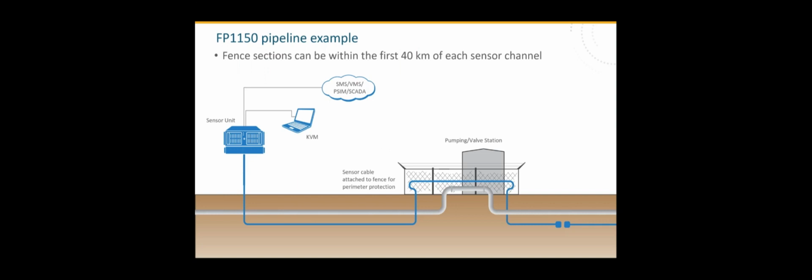And because the system is general purpose, you can do what the picture is showing here, whereby this cable is being used primarily in this little vignette for the pipeline TPI detection application. But at the above ground infrastructure points, which could be valve stations, pump stations, power stations, that same cable or the same fiber path can be deployed on the fence to give coverage of the above ground installations with no infrastructure other than this fiber required at this point. No communication connections, no power, no grounding, no nothing.